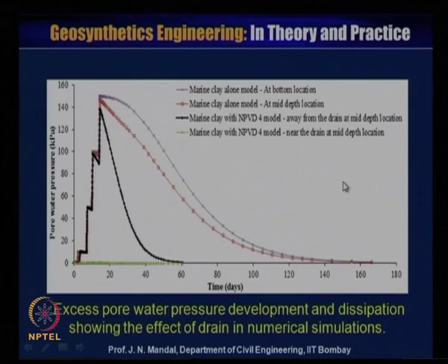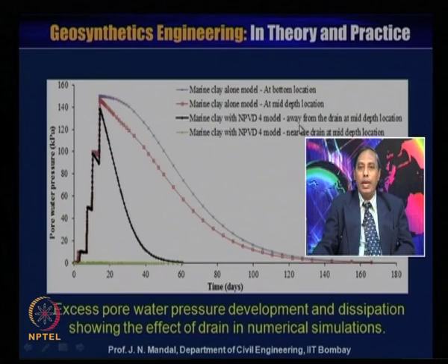Here is the excess pore water pressure development and distribution showing the effect of drain in numerical simulation. Here is the pore water pressure with time. This is for the marine clay alone model, then the marine clay alone model at mid depth of the location, and the marine clay with NPVD4 model away from the drain at the mid depth of the location, and the marine clay NPVD4 model near the drain at the mid depth of the location.